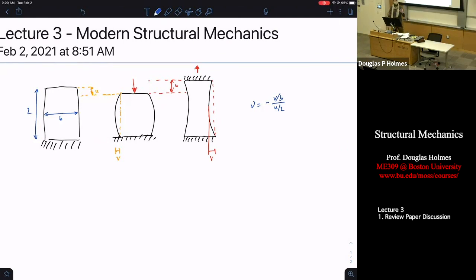Cork has zero Poisson ratio. Push on it, and it doesn't get fatter or shrink in either direction. This is why cork makes a nice stopper. As it expands or contracts in the vertical direction, it's not going to let air through on the sides, so it makes for a nice material for plugging a liquid vessel.